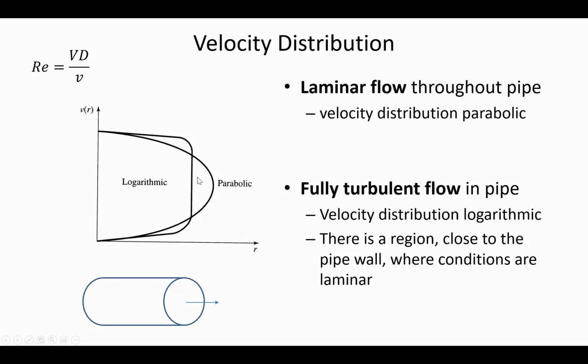There's quite a lot of variability in turbulence, and so this solid, even line just represents an average over time, where the velocity at one instant maybe would be a little bit less than the average, at the next instant would maybe be a little higher than the average. Over time there would be some velocity at the center of the pipe, but the closer you get to the edge of the pipe, the velocity is lower.